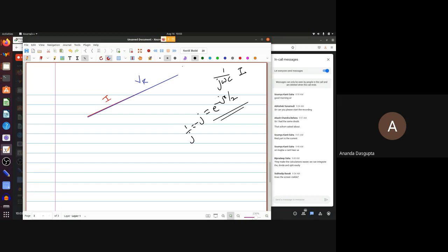That means that this particular piece has a phase lag of 90 degrees. So this is what the capacitor voltage would look like. And then you would join these two ends, and this will be VR plus VC. And of course, VR plus VC is simply the total input voltage, E.